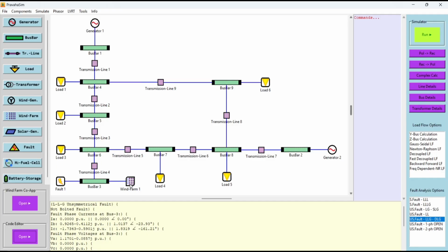And the wake effect also reduces the power, so the wake effect is also a very crucial parameter. So after calculating the wake effect and watching the wind speed, if the wind farm is not able to supply the required power, meaning if there is a load and generation mismatch, then the system frequency may not be stable.